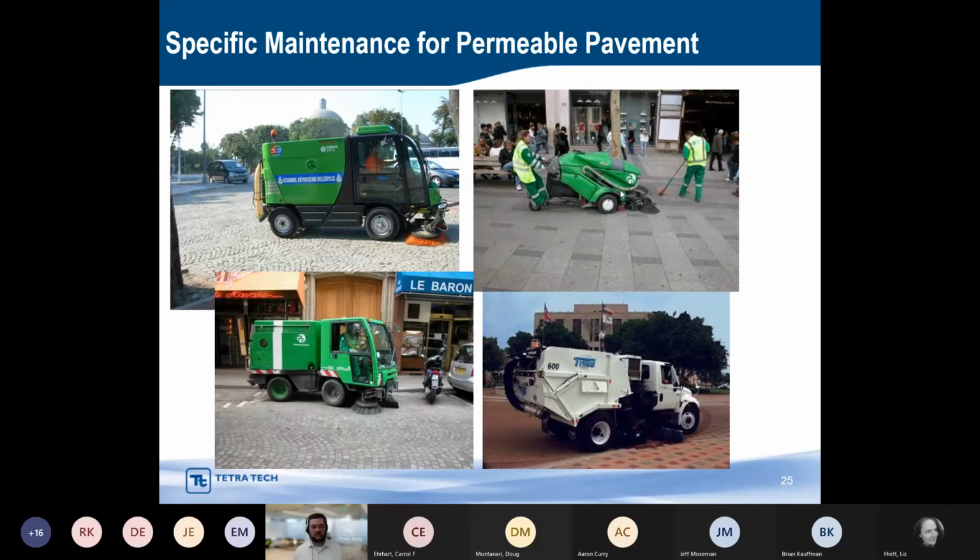If you have something in a right of way and you're sweeping your streets every couple of weeks, then a mechanical or regenerative air sweeper should function well to maintain that BMP. Regenerative air is a little better, so it helps pick up a little bit more of the sediment. If you're doing that even monthly or so, then you're great.